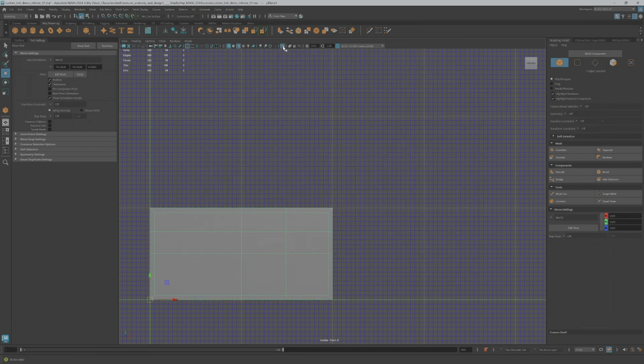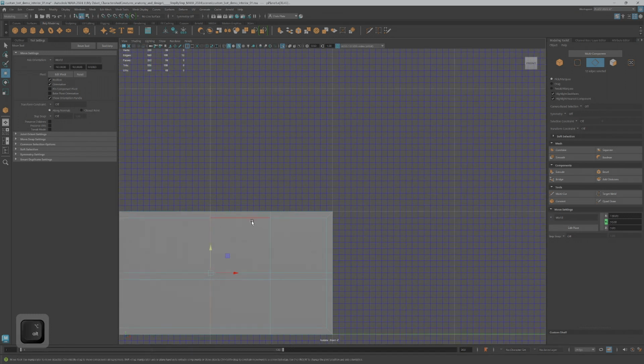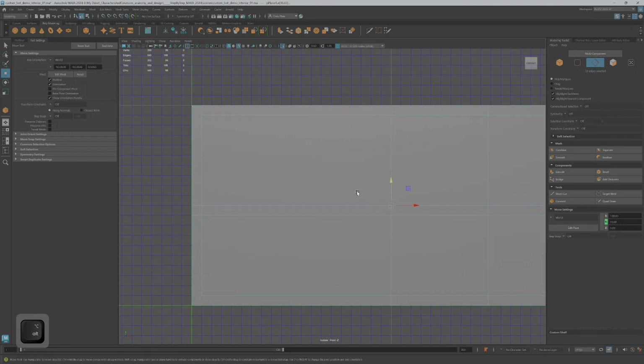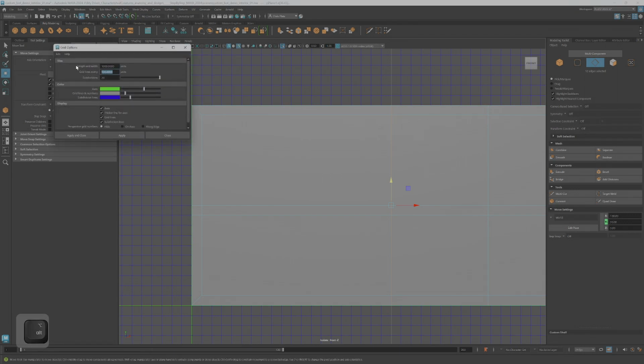Okay, we'll go look at it from the front view this time, since we're working in front view, and turn on and off the isolation mode. So grab these edges, double click, and we'll bring them down. One, double click, and hold down connect. There we go. And then the next one here, we need to subdivide the grid one time so that we can get this centered. Otherwise, it's going to be off because this is the middle edge loop on there. And we can double check that here by, instead of every 100, we go every 50. Apply. See, that's our center line right there.